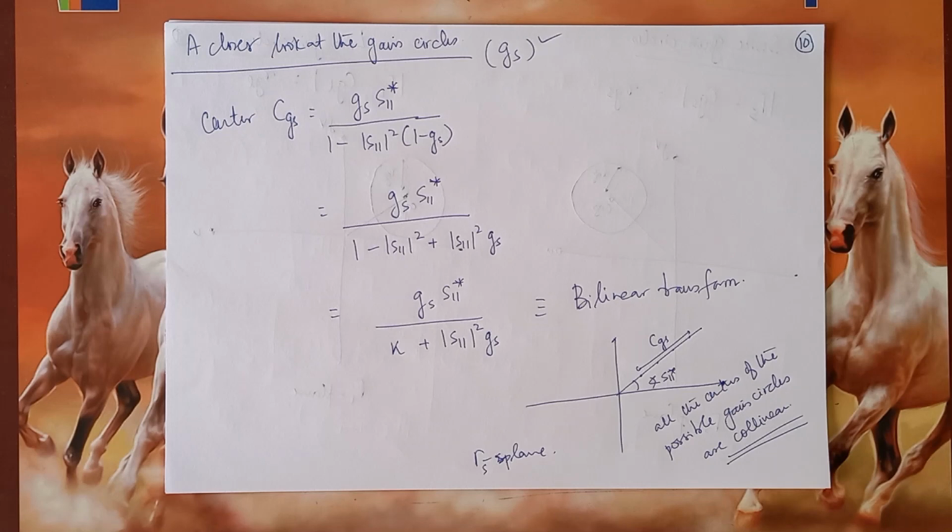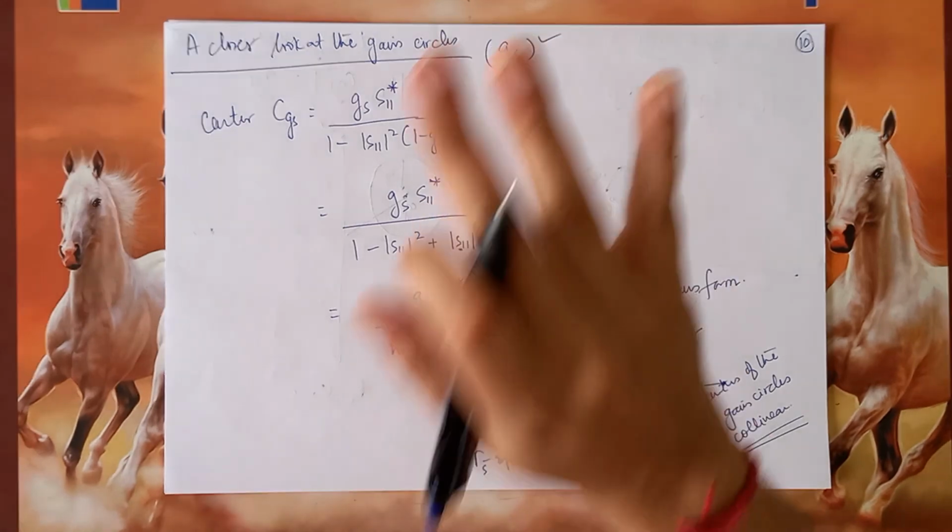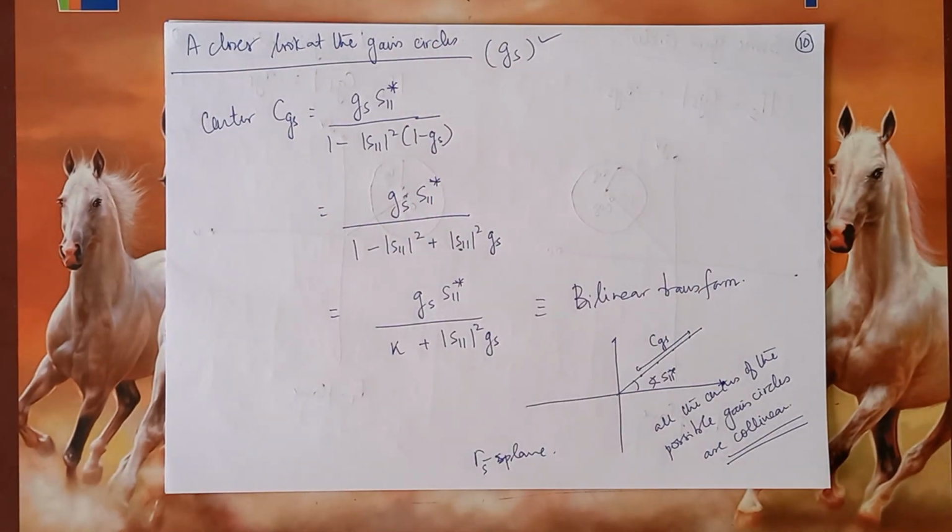So in this particular lecture, we discussed a little bit about the continuation of the stability aspect of MMICs. We discussed that from the stability angle, it is important to have non-unilaterality, which will give some flexibility to the designer. We need S12 not equal to 0, but for gain calculations, we would prefer S12 equal to 0, as the analysis becomes a lot easier.